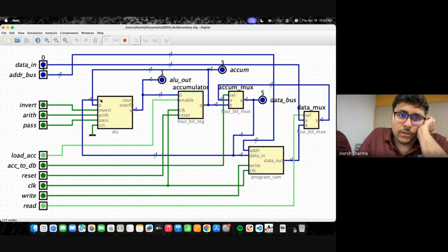Let's close the pass feature. Right now we have 5 at A, 3 at B. It's 1 because, as we know, right now it's doing bitwise AND. So it's showing just 1. So this is A and B. A is 5, B is 3. So to subtract, we first invert and then we add 1. So we get our output E, which is B minus A. 3 minus 5 is E in hex.